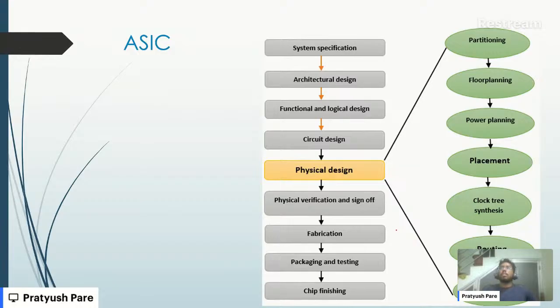So for setup, you need to have a minimum frequency or a minimum time period such that the data from one flop to the other flop gets transferred correctly. If you don't have it, then that is a setup violation. We can have a session and I can explain very clearly. Yeah, and it is asked many times in interviews. It is a very good concept and a very deep concept to learn. It's not just setup and hold, you have lots of things.